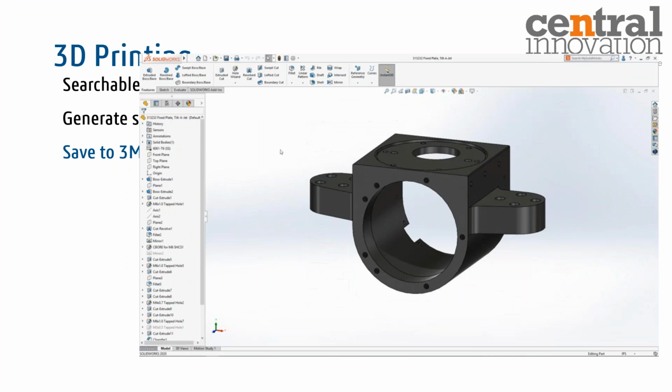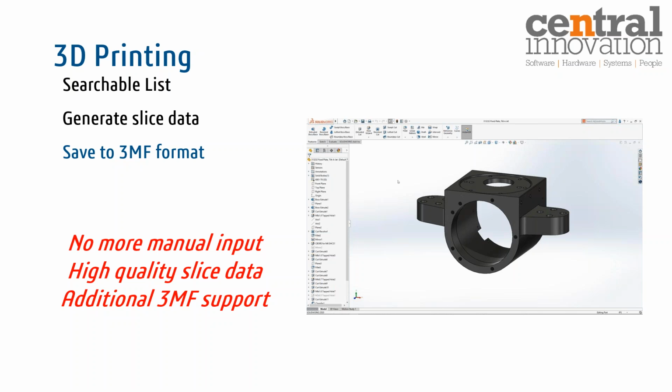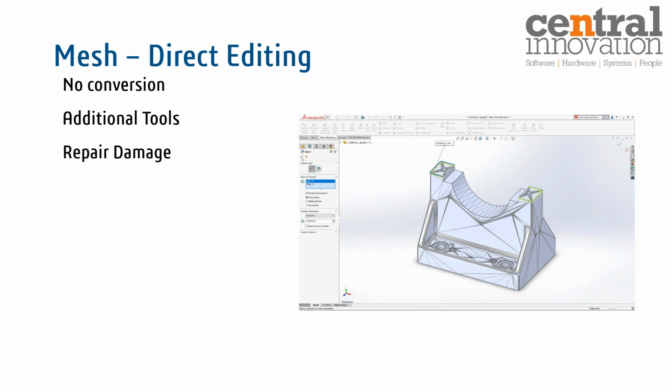The other enhancement I will talk about here in SolidWorks is dealing with the scan data. Dealing with the scan data was a hassle for a long period of time, but starting from 2018, SolidWorks has added several features to a tab called Mesh Modeling, which allow you to manipulate the mesh files and do some changes in the mesh file, and even you can save it as another mesh file later on, or you can convert some of these meshes to be faces and solid bodies.